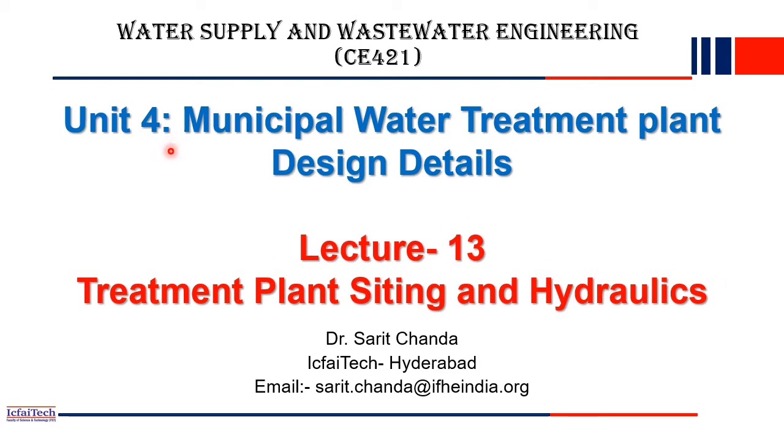Up to last unit, Unit 3, we have discussed the different units present in the municipal water treatment plant. Starting from screenings, then you have the aeration tanks, then the primary sedimentation tank, then the coagulation flocculation tank, right? Then you have the secondary sedimentation tank. After that, water will go for disinfection. So these are the different units we have discussed in detail in the last unit, Unit 3.